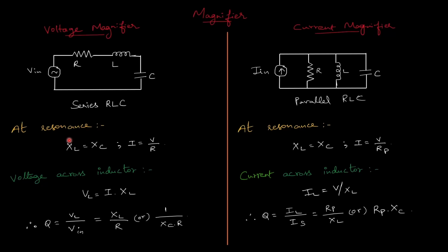In our previous videos, we learned that an LC circuit can resonate when XL is equal to XC, but resonance has another fascinating property. It can make a voltage appear much larger than the source voltage, and it can make a current appear much larger than the source current. Today we will study two important resonance phenomena, the voltage magnification and the current magnification. We will derive the equations, design the circuits, understand why Kirchhoff's laws are still valid, and finally discuss why these circuits are not practical amplifiers.